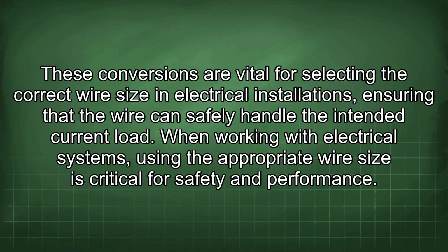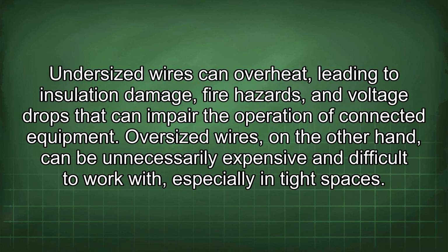These conversions are vital for selecting the correct wire size in electrical installations, ensuring that the wire can safely handle the intended current load. When working with electrical systems, using the appropriate wire size is critical for safety and performance. Undersized wires can overheat, leading to insulation damage, fire hazards, and voltage drops that can impair the operation of connected equipment. Oversized wires, on the other hand, can be unnecessarily expensive and difficult to work with, especially in tight spaces.